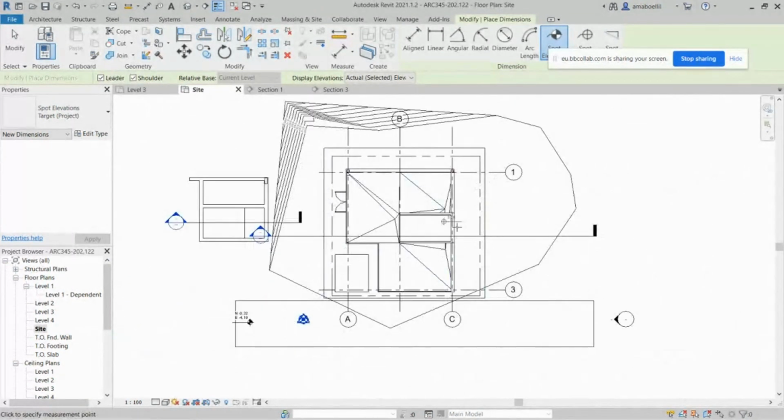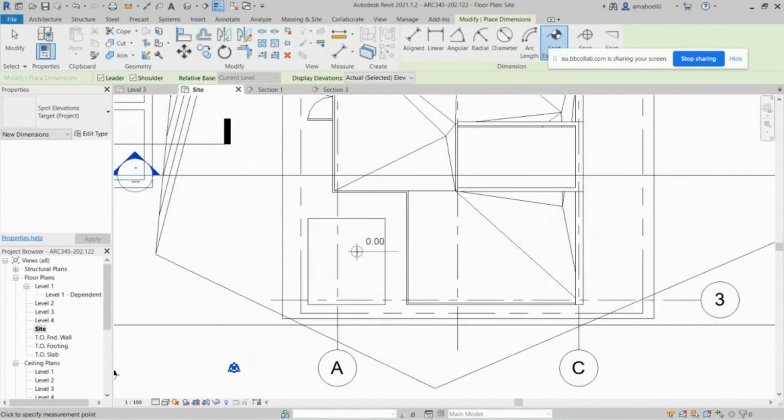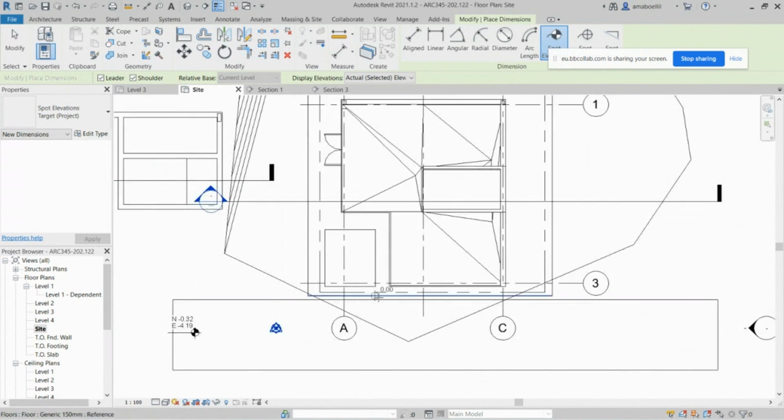Of course, when you build your slabs that imply tiles and greenery and the street, you have to make them apart from each other, or level from each other. They cannot be the same level, because if you have a street and you go into a curve, at least you will have 15 centimeters elevated this from that. So you have to pay attention to these differences in levels.